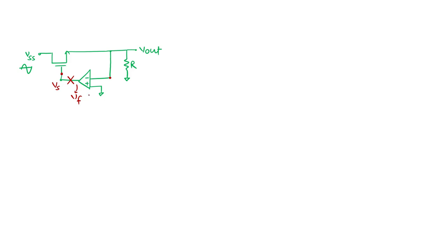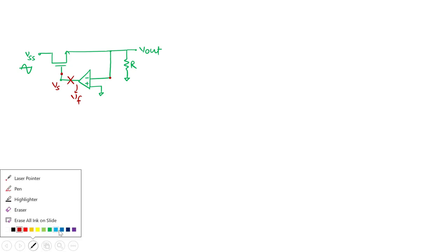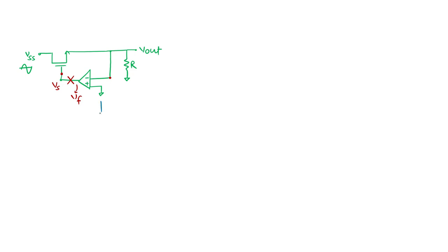But I want to consider my amplifier in the feedback factor. This is my amp, and I want to consider it in the beta factor. That's why I broke the loop here. You can break the loop here also, but in that case the negative feedback will remain 1, so beta will remain 1. By breaking here, we can take this amplifier in the beta factor itself.